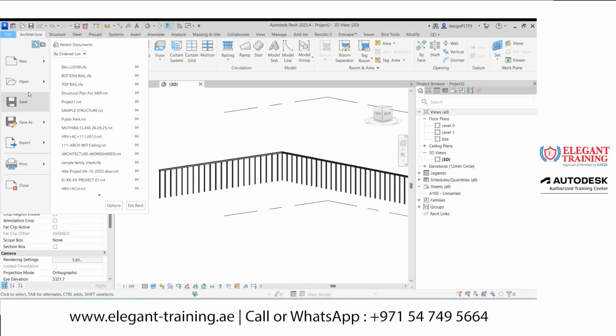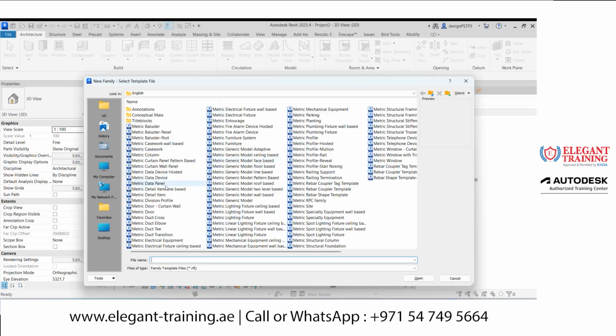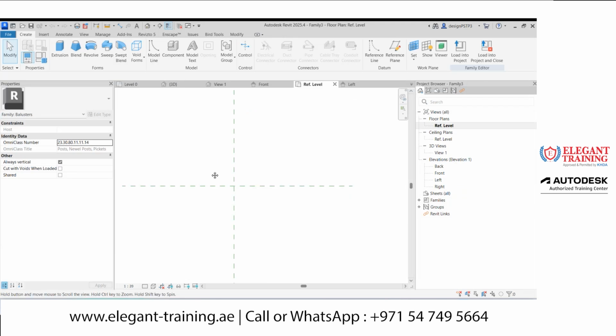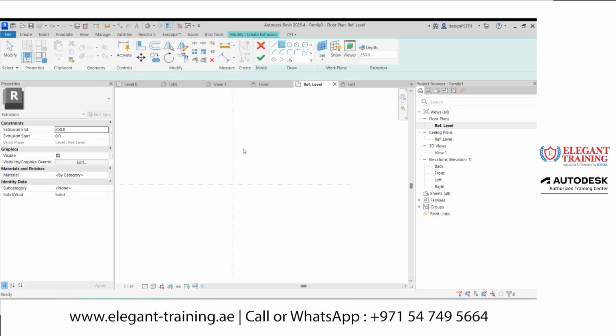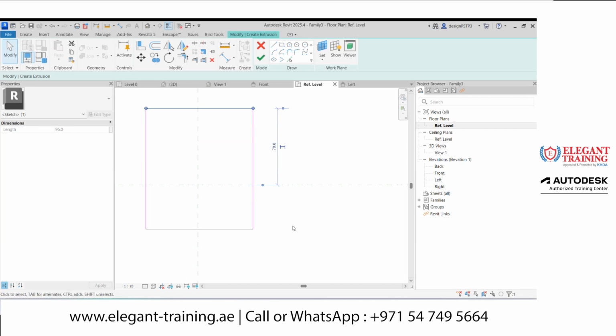So again, I can go to File, New, Family. Okay, I'm going to choose the baluster post. Open. I can draw an extrusion, and how to make it in the center? If I select this one, here you can see the witness line. I can place it here and I can mention this one as 70.